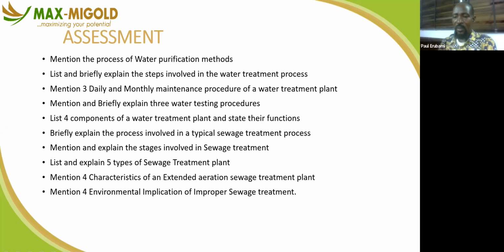In that PVC pipe, there is something they call the casing screen. The screen is where the water enters the column or pipe. The screen is done in such a way that it has very tiny spaces where only water can come into that column. There are some situations where those holes get blocked, either by dirt inside the borehole, or if you have what we call clay alteration in your water, it's possible.